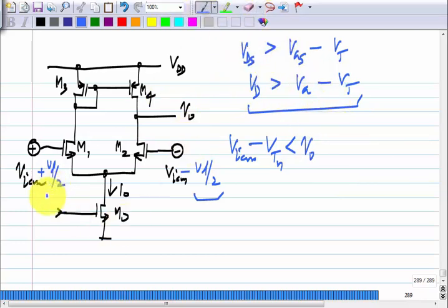And let us say because of applying a positive VD, V naught keeps rising, then what happens? Which transistor gets into trouble? M4, right, very clearly, because this is fixed, this is rising. So, this voltage across M4 is getting smaller and smaller and M4 is getting squeezed. Okay. So,